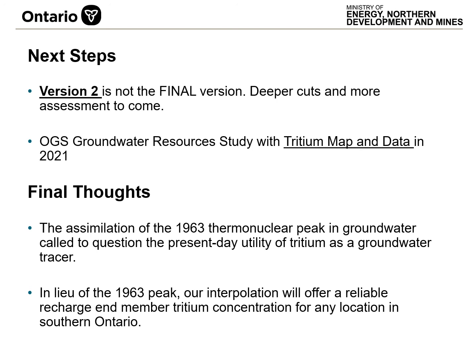So tritium was a very useful tracer prior to the assimilation of the 1963 bomb peak, but since then it's become difficult to make groundwater age estimates without also collecting helium data. What that 1963 peak provided us was a really useful time marker, and what our interpolation offers is an alternative marker, a location-specific recharge end-member tritium that can provide context for interpreting groundwater tritium values in systems anywhere in Southern Ontario.